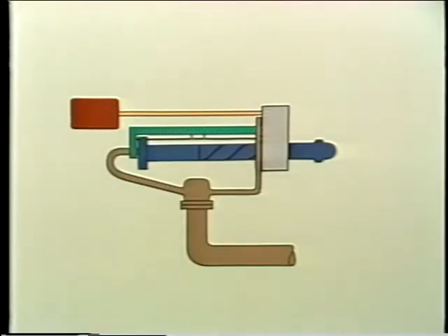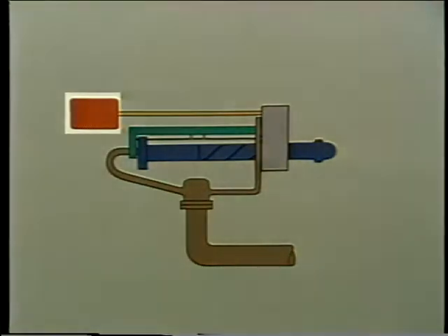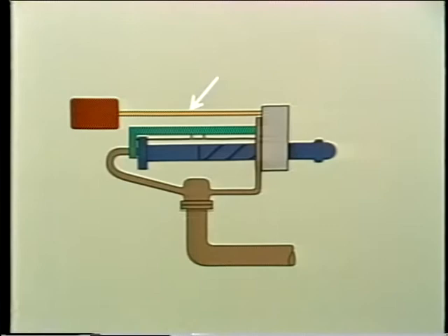The fixed drive mechanism we'll use as our example here is a system used to drive a short tube retractable soot blower. This one is operated by a motor mounted at the end away from the element. A shaft from the motor's gearbox drives the main drive gear at the other end where the element goes into the boiler. On a stationary rotating soot blower, this drive gear only has to rotate the element during the operation of the soot blower.